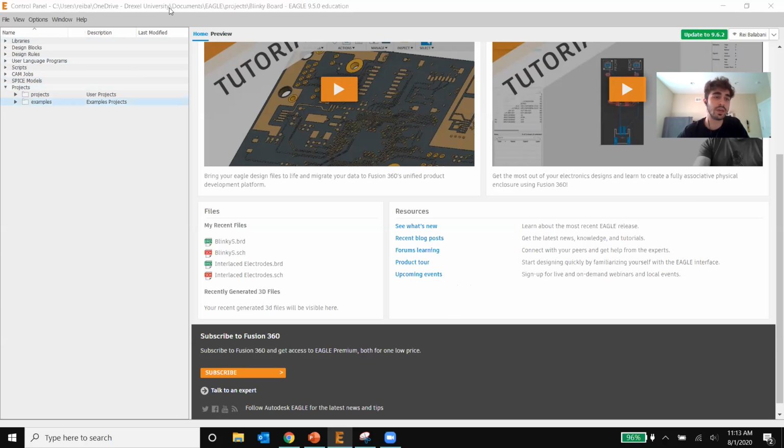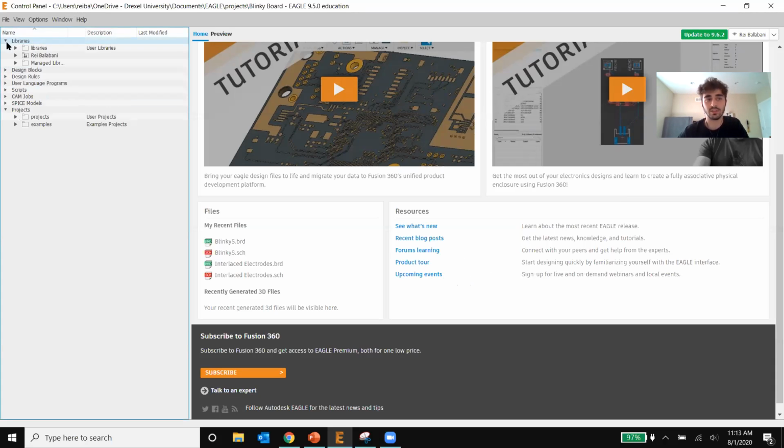But here on the side, we have this drop menu, and now we have libraries. What are libraries? Libraries are basically folders which contain components that are already built in. When you want to drag, for example, a capacitor, you drag it from the RCL library, grab one from there, and put it into your schematic.